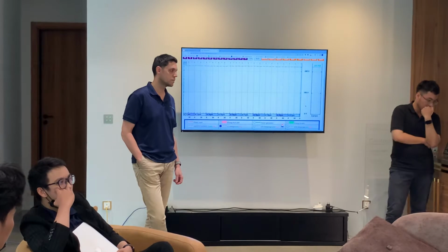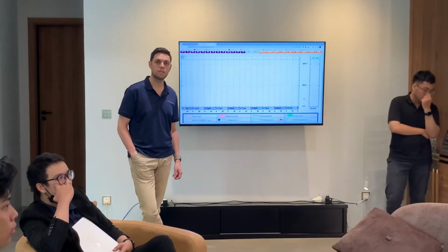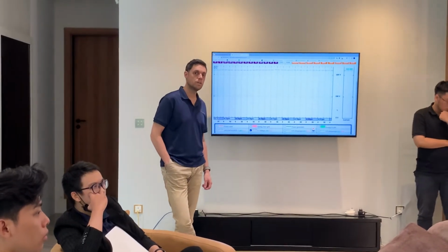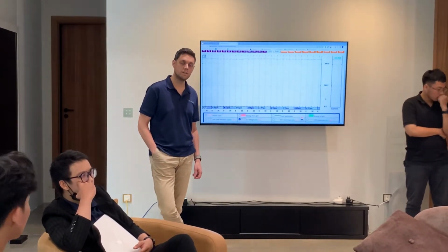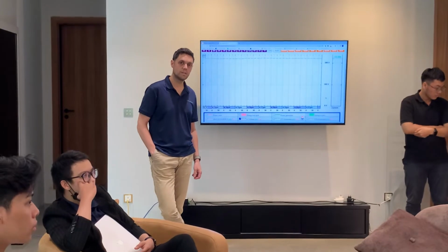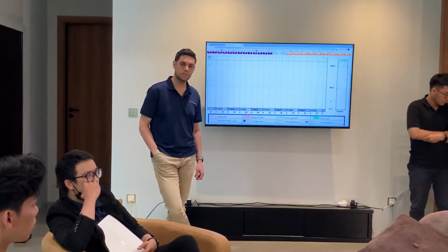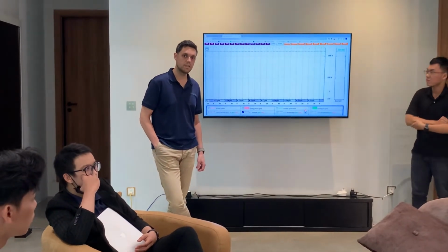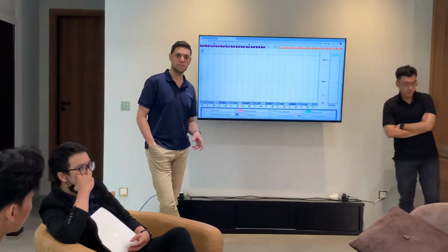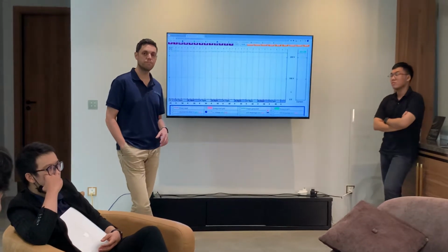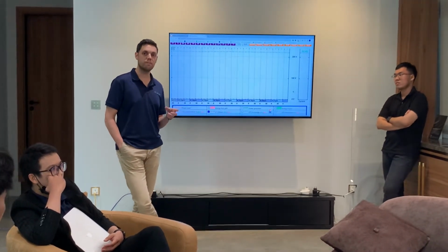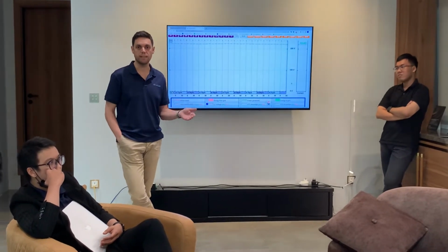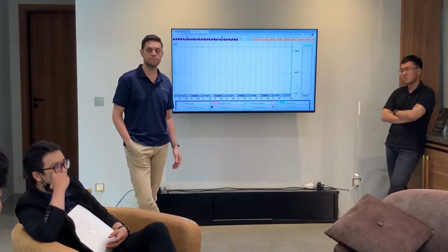I think the core is the small one, 15, right? Okay. So that means if we have like 5 water pumps that we're doing, and all of them are 3-phase, its maximum can only measure 5, correct? Yes. Okay. So that is for exact measurement, right? Now you can fool it and just measure one phase and then just multiply it. Okay, so that's how we are doing it, right?